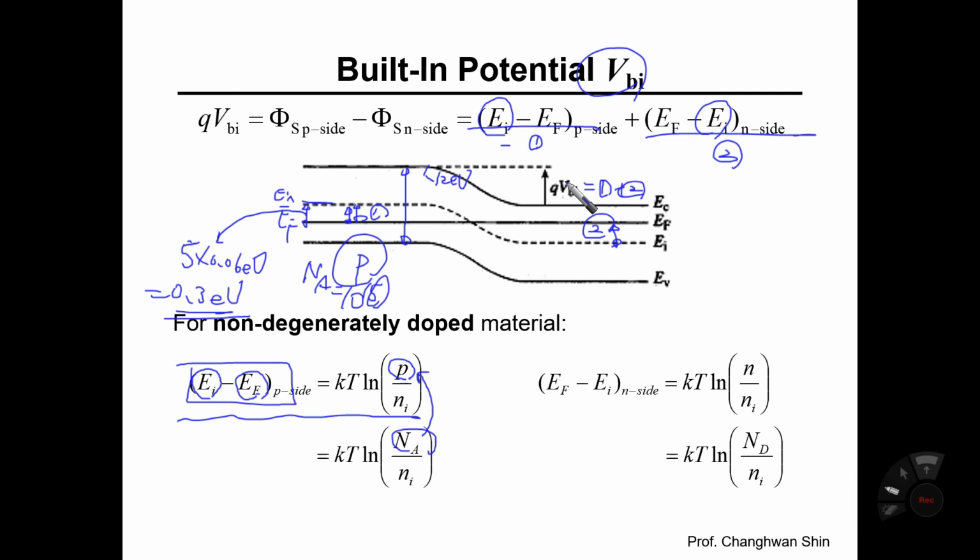the P-type is making a contact with the N-type silicon material. So this built-in potential concept can be easily and intuitively understood with two different dishes. One dish has a smaller amount of water, and the other dish has more water. Then the water surface height difference would give us the idea of built-in potential.